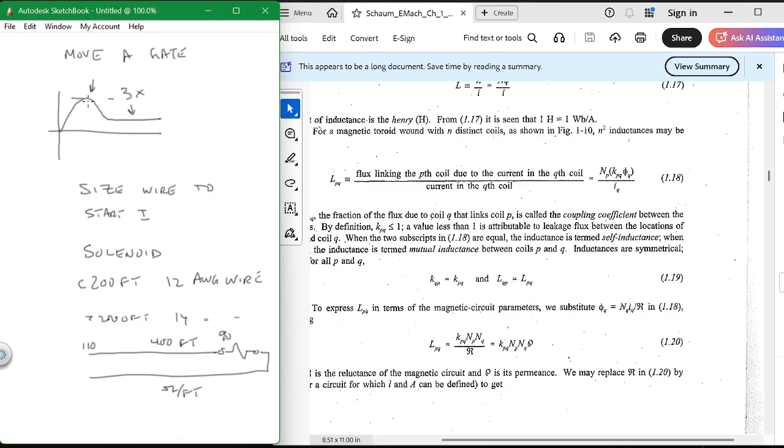But the B that you're going to see, the actual magnetization force that you have there, the B force, is you've got to have enough to get over this hump. And you've got to furnish enough current to do that. In order to do that, you have to go to a bigger size wire many times, and that's why. Okay? Again, that is a very practical application of this concept.